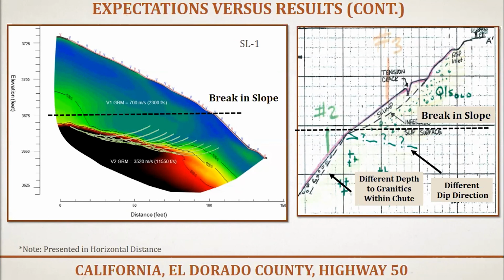The differences in what we were able to gather from the seismic refraction survey as compared to the expected structure shows the value of having geophysical data before the design process. Without the seismic refraction data, the slope may have had a very different mitigation design or a construction phase with costly unexpected subsurface conditions.